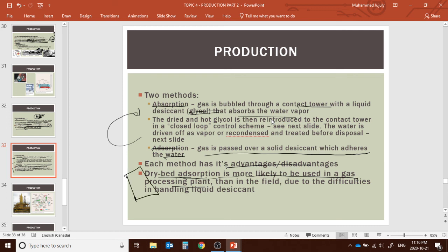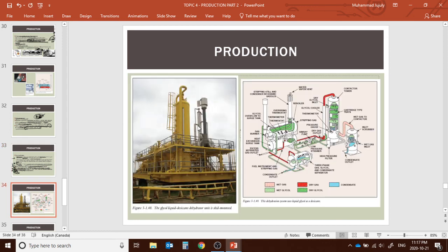Okay, the reactor looks like that. It has a packed bed inside, so you put the gas through, and it goes through a pressure cycle, and after a cycle the dry gas comes out, and the moisture is trapped in. Then there's a regeneration time, so we heat it up again and remove the steam, remove the vapor outside, and then we use it again. It's less complicated to use the adsorption technique.